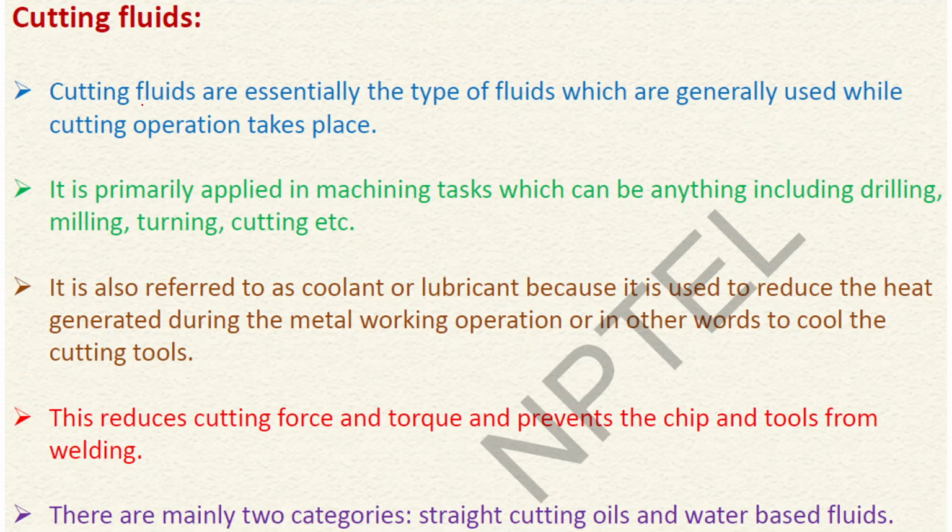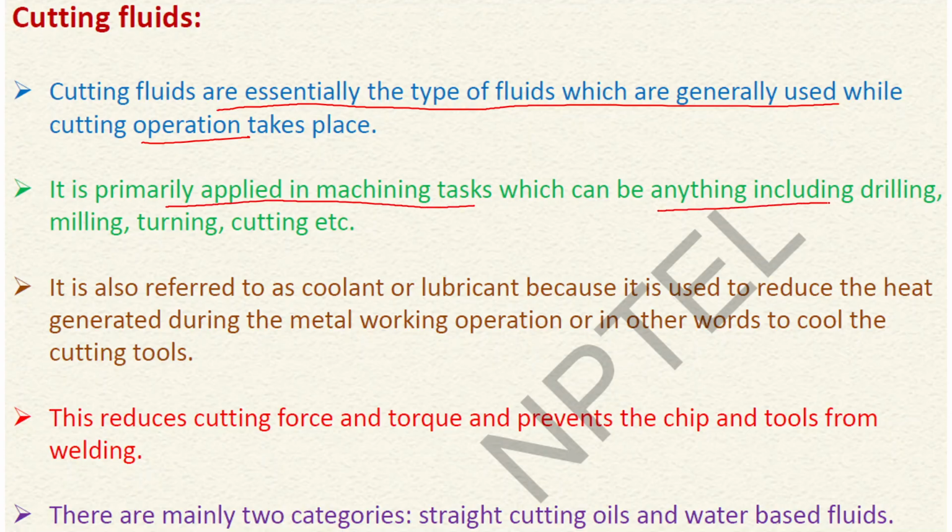Then the cutting fluids are essentially the type of fluids which are generally used while a cutting operation takes place. It is primarily applied in machining tasks which can be anything including drilling, milling, cutting and turning. So where drilling, milling or cutting kind of actions take place, there this cutting fluid is used. It is also referred to as coolant.